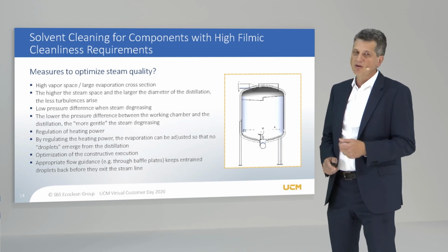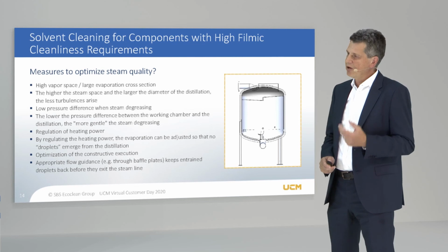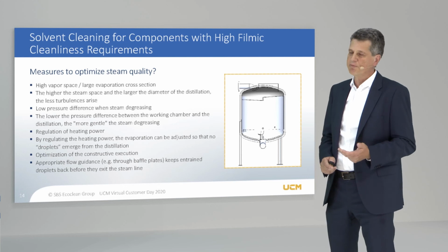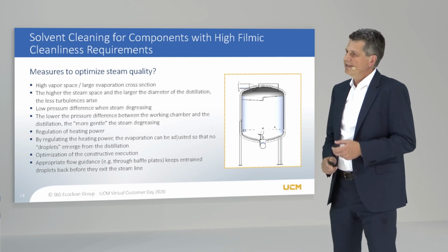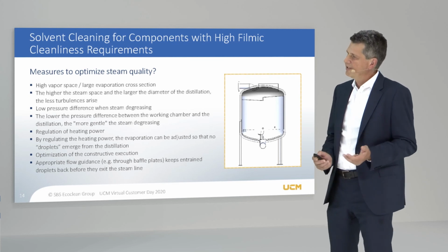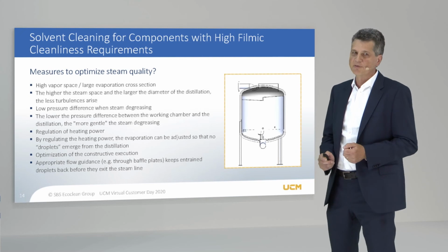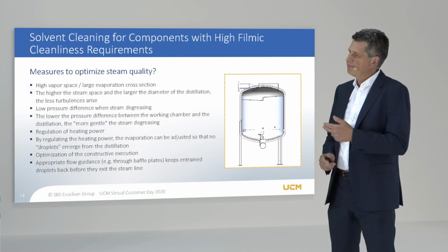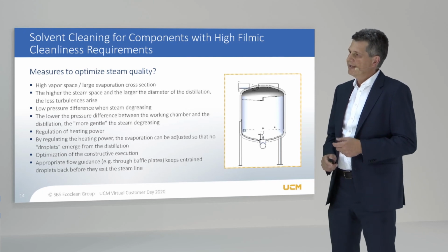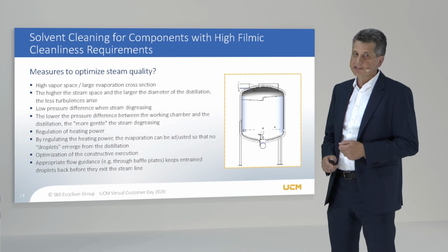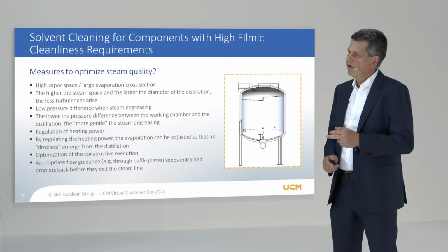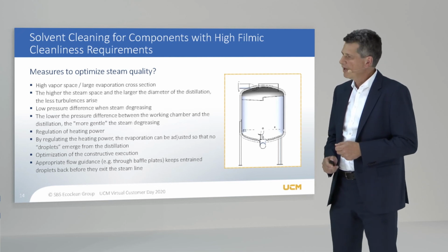So we identified all the parameters which concern the quality of the vapor, and these are the height of the distillation tank, the evaporation surface of the solvent, the pressure difference between the working chamber and the distillation, the heating power that we introduced to the distillation, and of course the flow of the vapor.